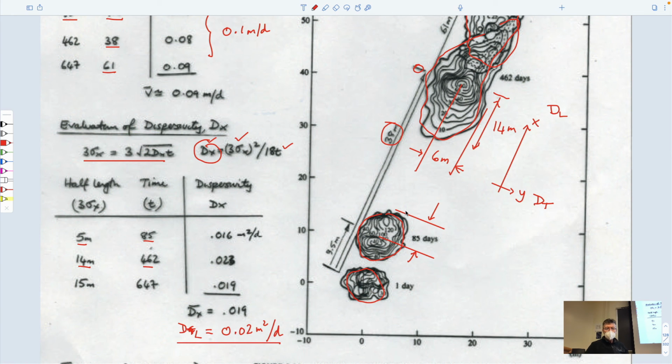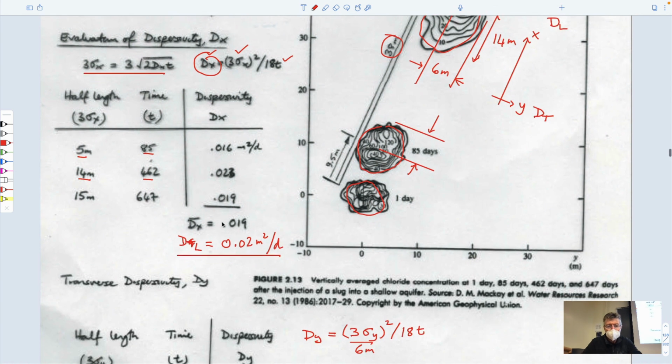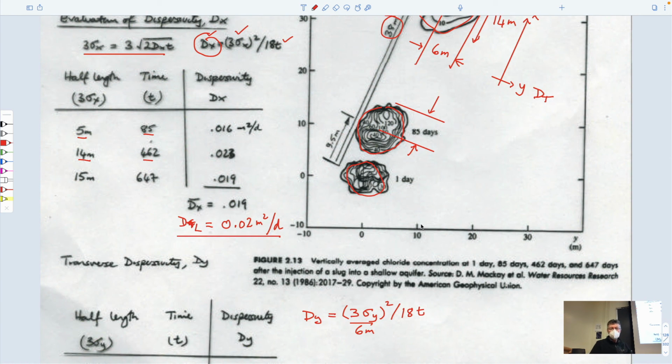And also remember that the velocity doesn't come into this term at all, really. But if we wanted to calculate from this the magnitude of this value alpha, remember longitudinal dispersion is equal to the Fickian term plus alpha L times V in x. So we just calculated this.